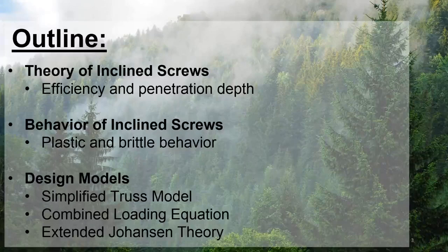The focus for this advanced webinar has a lot to do with the relative proportion of dowel effects and axial effects, as they both contribute to the total connection strength for inclined screws. This webinar is going to start off first with a little background theory, and then we'll go into examining the three design models which I have listed over here, and those are the simplified truss model, the combined loading equation, and the Johansson yield theory.